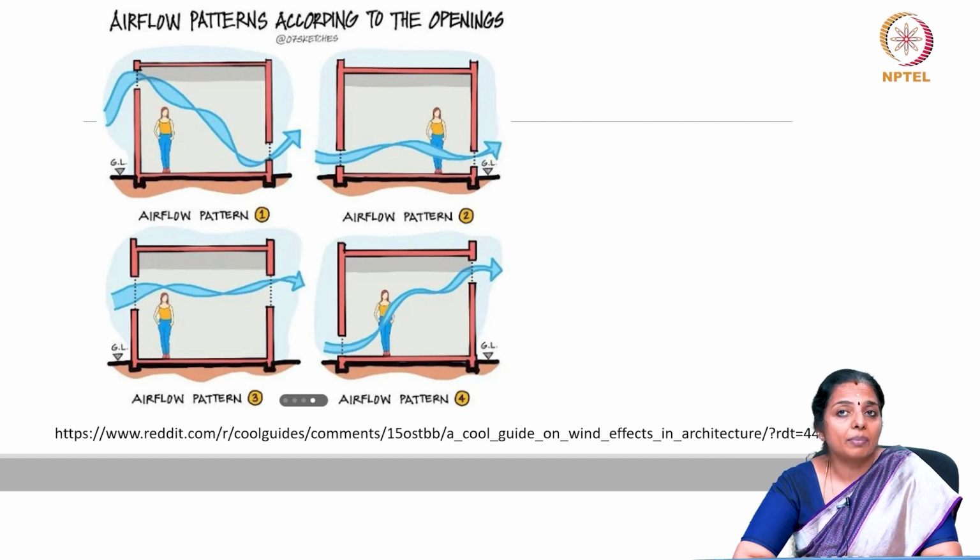The fenestration pattern and configuration involves the area, shape, location and relative position of the windows. This would affect the air movement, daylight and glare indoors. If unshaded, the area would also affect radiative heat gain. Based on where you want the air to move largely in the room, you must plan the location of inlet and outlet, and you must also plan the size of the inlet and outlet.